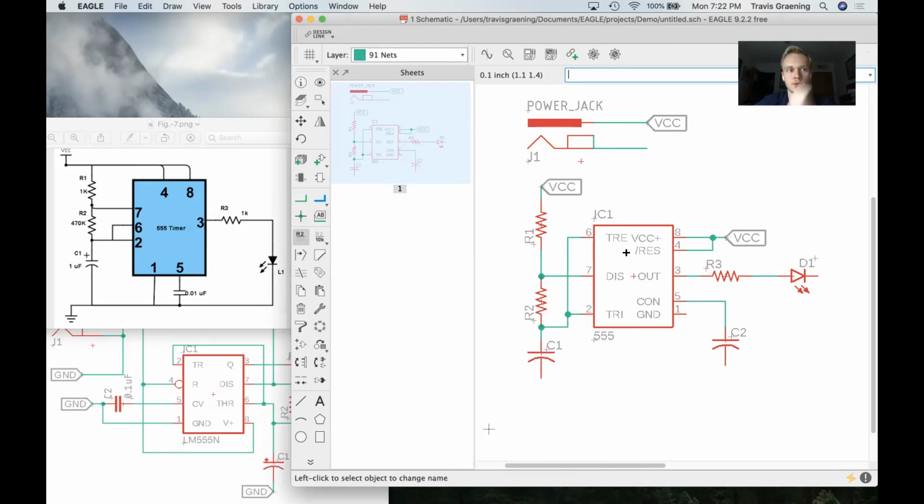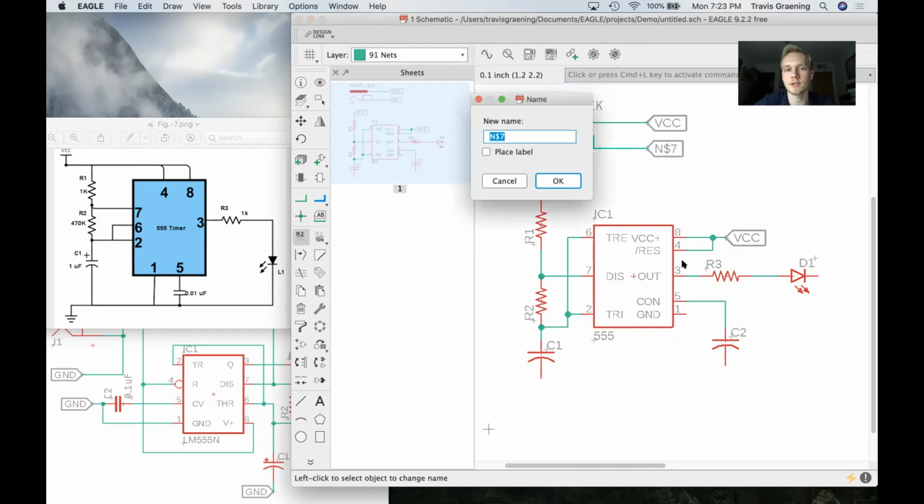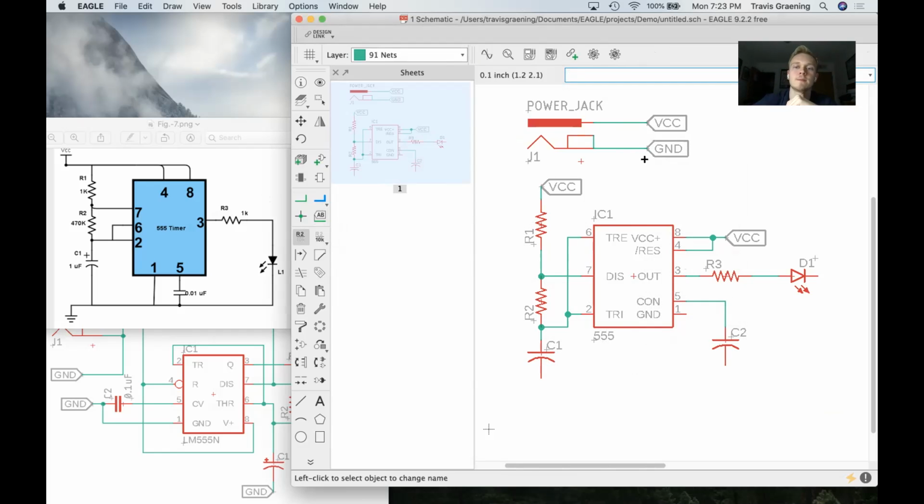But now it's time where I have to connect all of my grounds. We're going to do that by creating another label right here, which we're going to name ground. Let's find that, ground, GND. And these are some names you guys should know. A really common representation for our ground is just that uppercase GND like this. So on most of your circuits where you have a connected ground, which will be all of them, you are probably going to want to use that as your symbol for it. One other thing to note is that VCC will always mean a power source. Some people will say VCC, especially if it's not a battery you're using, but it's perfectly okay to say power like PWR or BAT. It all means a very similar thing.